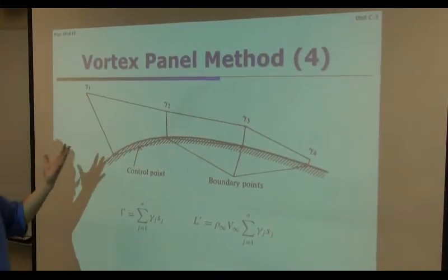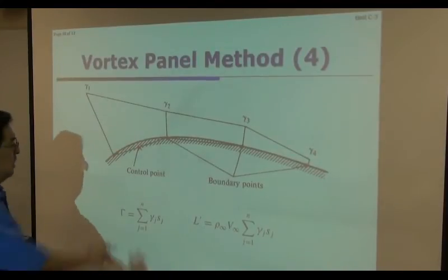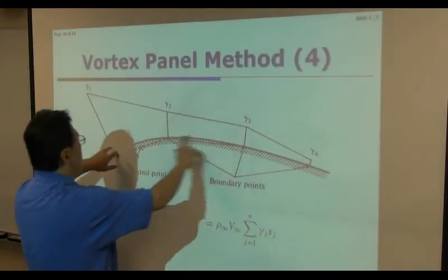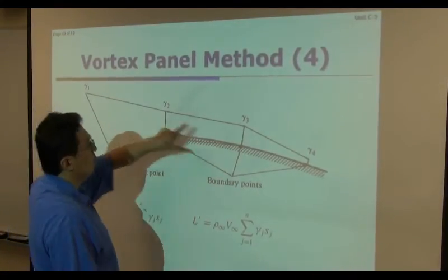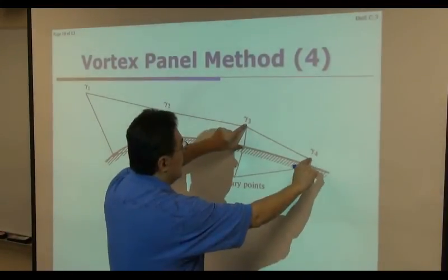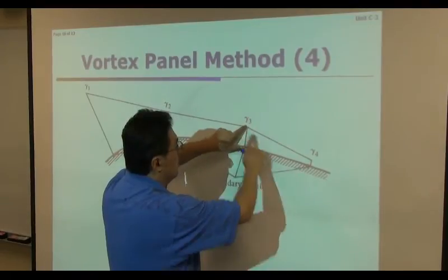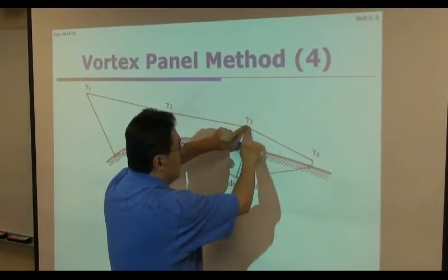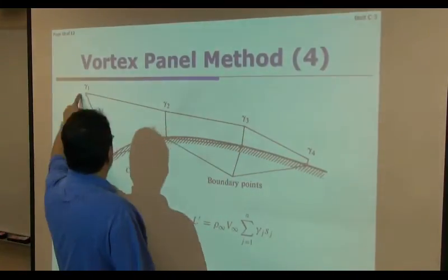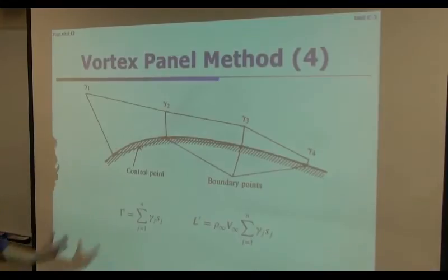We can have a second order code. Second order code is something like this. At the connecting point of each panel, you are going to have a common amount of circulation. So within those two values, from left to right of each panel, you are going to change the amount of circulation linearly, so smoothly connecting the distribution of circulation over the surface.